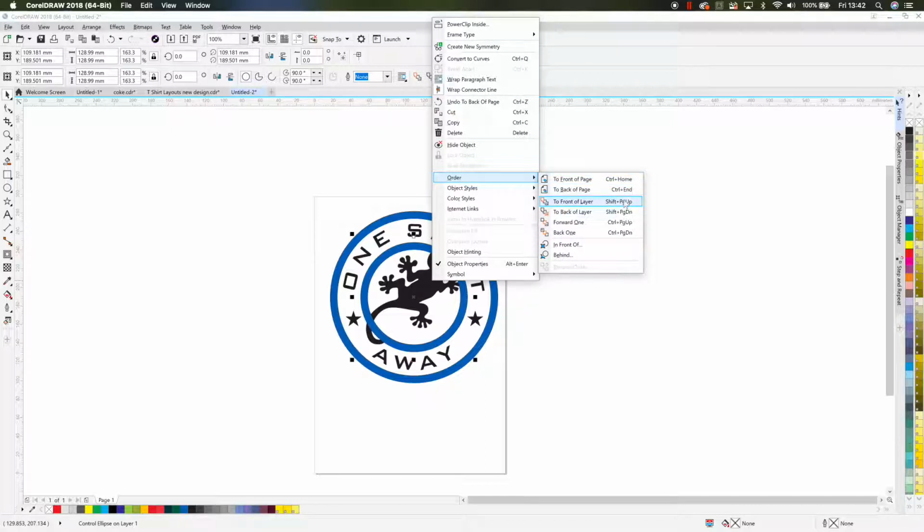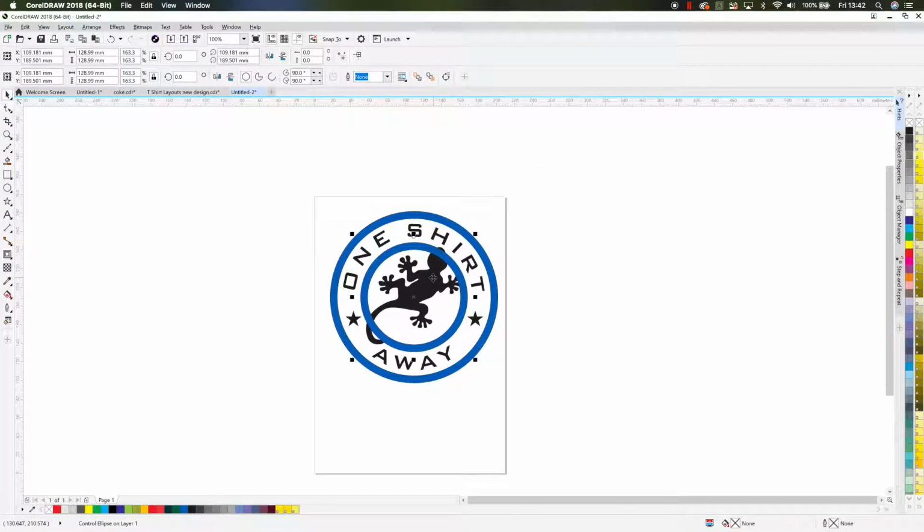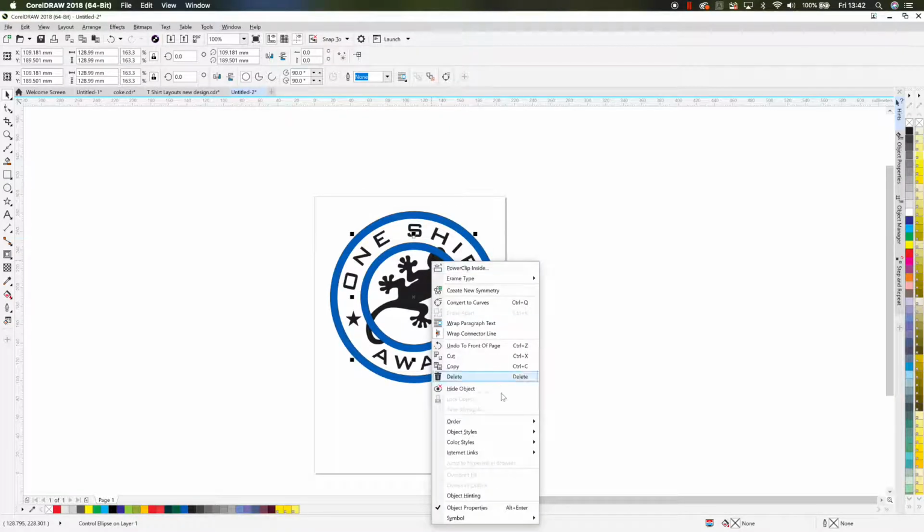It's highlighted. We can move it one layer at a time, so it will move through components, and that is Shift, Page Up, Page Down. Or we can go Control, Page Up, Page Down, sorry. So let's just do that. Let's go Control, Page Up, and as I move through, I'm going Control up all the way at the moment until eventually I get to the front.